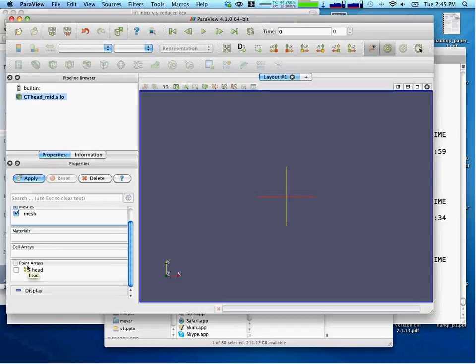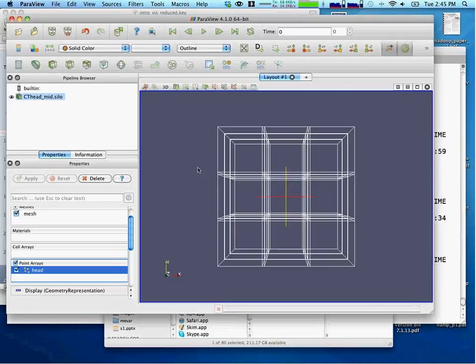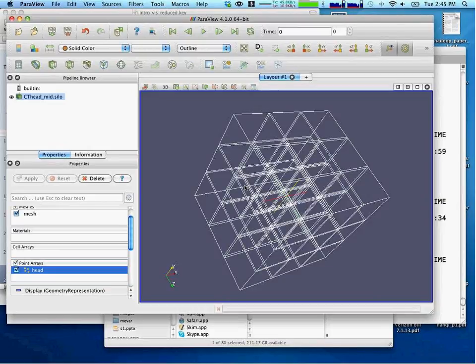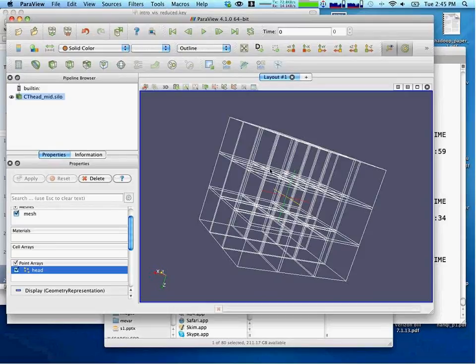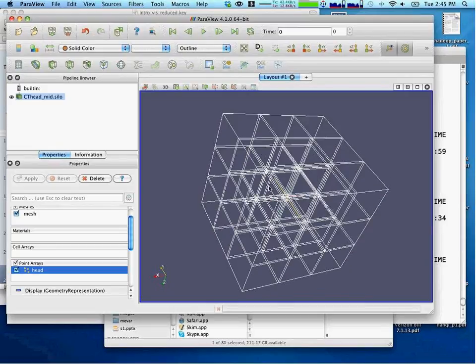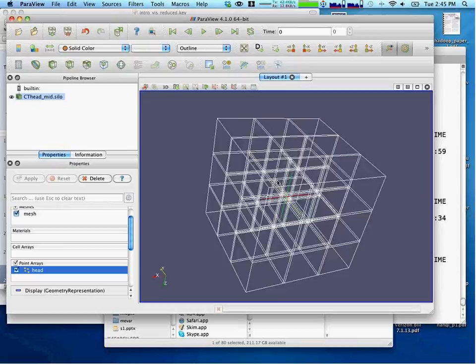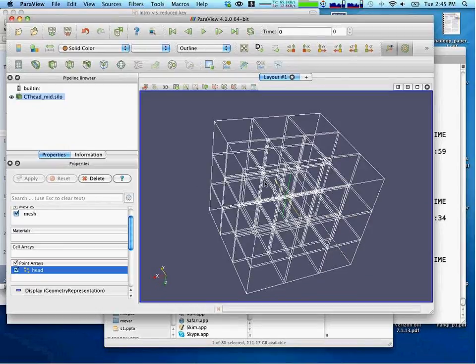Once we load in the data, you want to tell it, okay, what out of this data set do I want to see? Visit just kind of throws it up there for you. Here we're going to select our variable down here, click apply. This is the mesh. And what Visit didn't show you is that this mesh is divided into blocks. So 20 different blocks here.